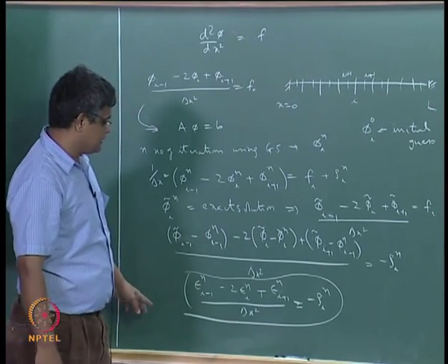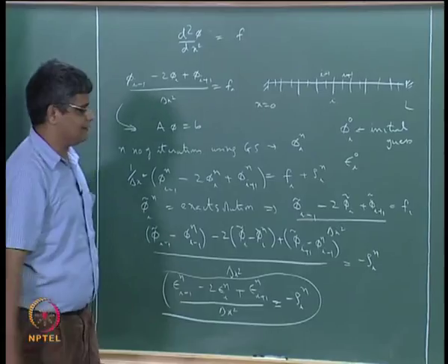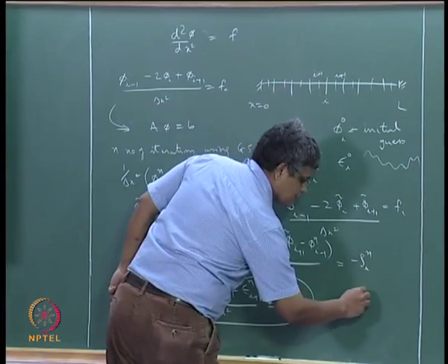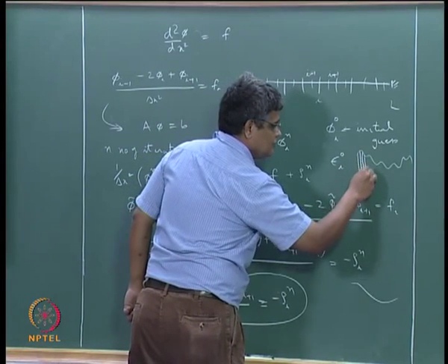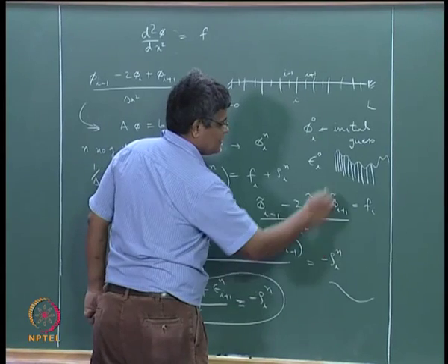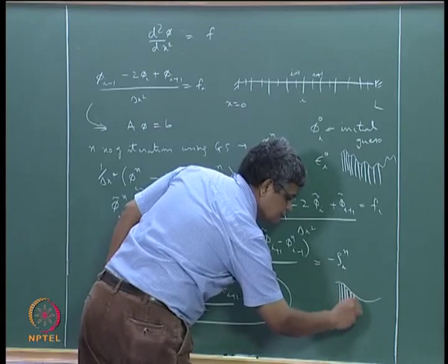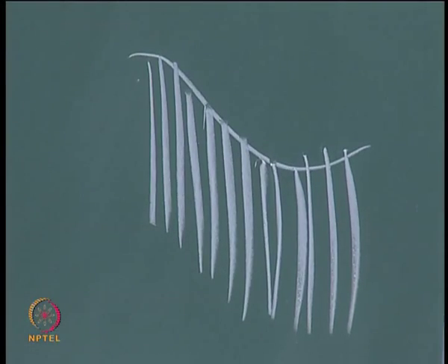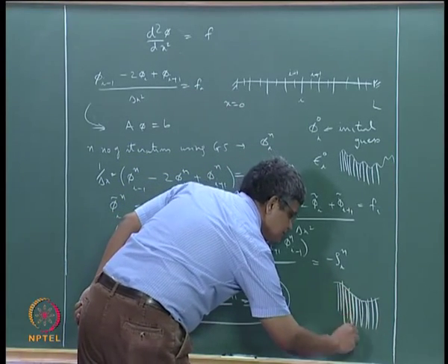So now what we want to do is that we are claiming that this is smoother than the initial error distribution, and therefore, whereas this variation can be like this, the variation for the same thing will be like that, and since this requires a small delta x here, the same thing will not be showing this much variation, and we will see that on the same delta x we have a smooth variation, where therefore we are saying that we do not need such a fine grid.